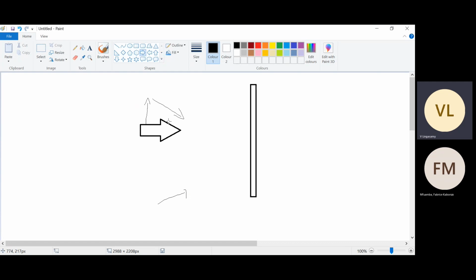So we are facing the issue that the coordinate system is something like this, but the waveguide port will work along with the coordinate system only. So when you move this, according to them we are giving the port position and everything, right? While simulating, it will take only that as a reference. That's why it could not simulate.